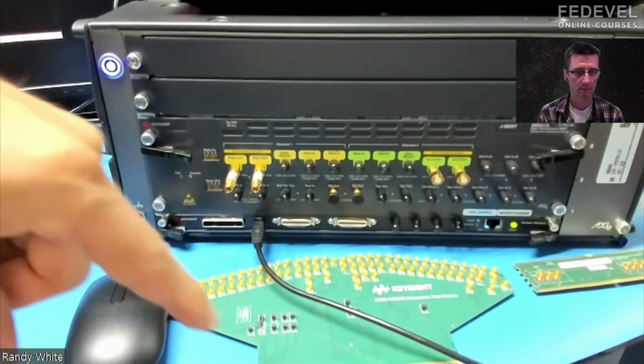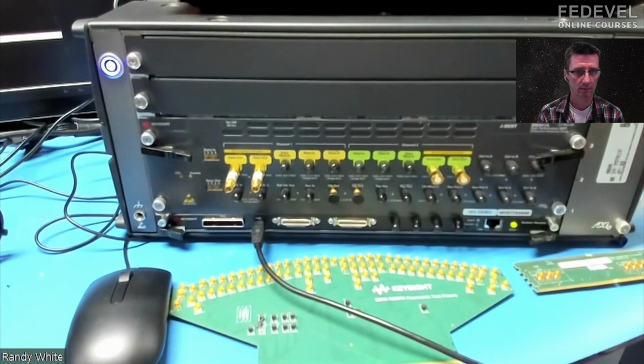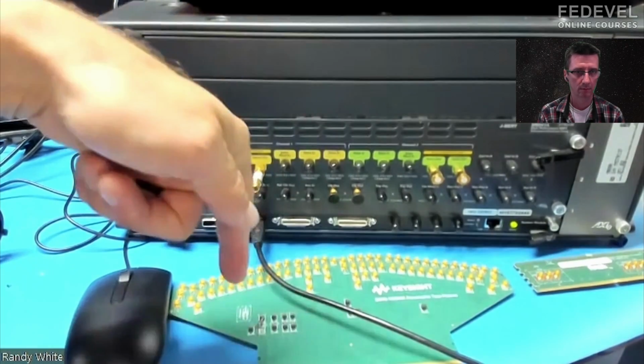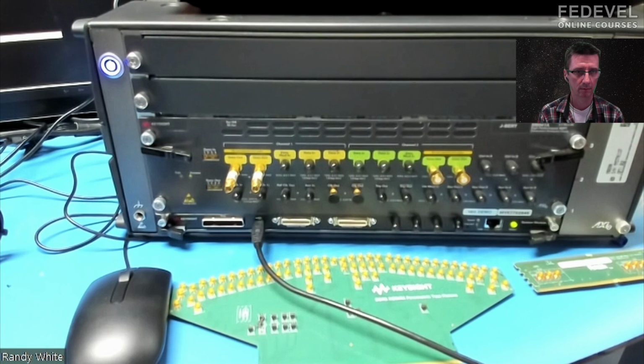It literally loops back whatever signal it detects, and the signal has to be latched as if this is the real signal that was received and detected and sent into the internal core. That signal instead, for testing purposes, is looped back, and then it goes back into this data input. So out, in, and the fundamental test here is the bit error rate or bit error ratio test.